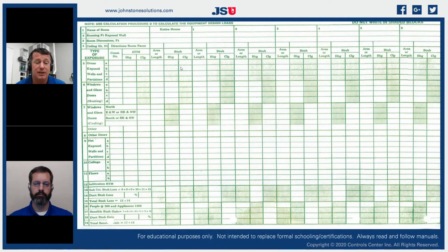And I actually had a conversation with a contractor here in Indianapolis where that is not required, but I had a contractor that he does a manual load calculation on every job they go on. Every estimate gets a load calculation, either a manual on a new construction or it gets an automated on an equipment replacement, just to verify that the proper size equipment is going in.